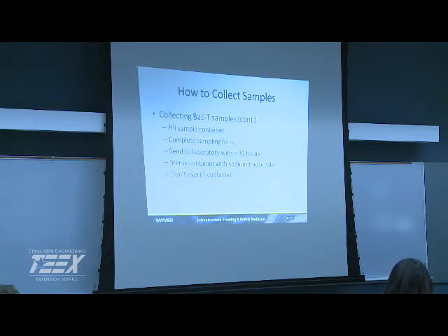I had a question Tuesday about wearing gloves, especially if you're pulling systems that pull a number of samples, and about wearing the rubber gloves, lab gloves and stuff. I recommend not doing that because people become complacent. They have their gloves on. Next thing you know, they're doing all kinds of stuff, and now they're over-handling the samples. Wash your hands well, whatever you need to do to prepare for your sample taking. Take it seriously. I take pulling a sample real serious. And it benefits you as an owner or operator of the system to pull the best sample you can.